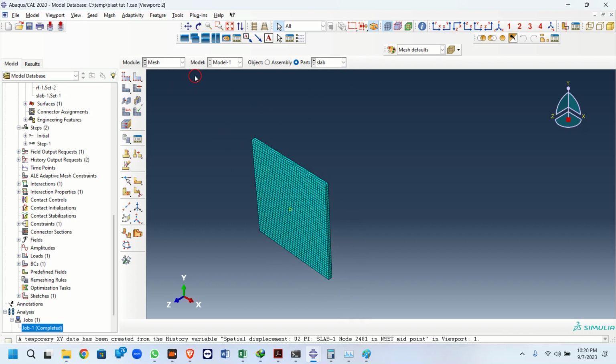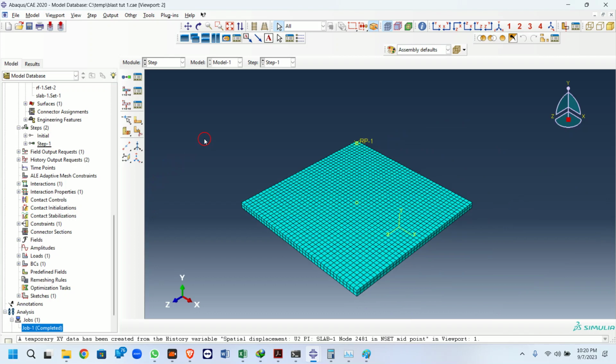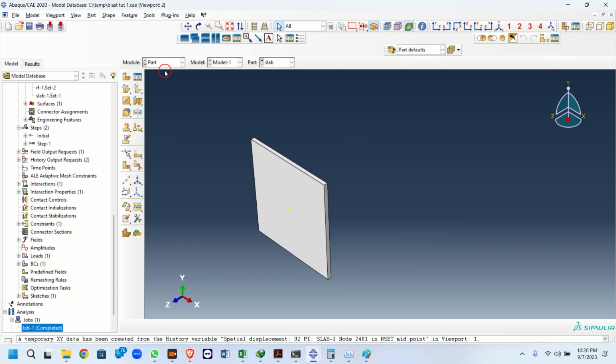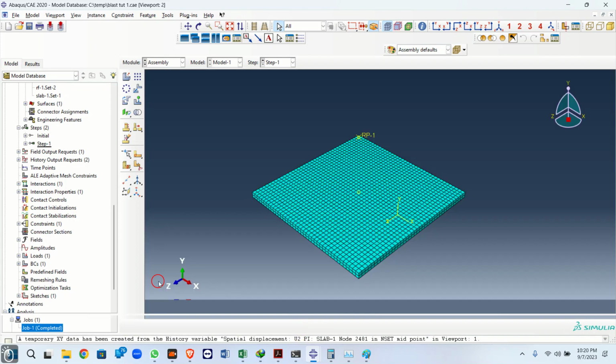Okay, so it is similar to CFD or any other FEM. So then you have two uncertainties. One is property, then the meshing. Once you have done with all this, then you can proceed with the other things. But why take so much tension, or you need to know all these things to calculate the exact pressure. So it's better, instead of going for all this, just find out the static pressure and apply it. Though that is a little bit overestimated, your model will not fail, your model will be safe.